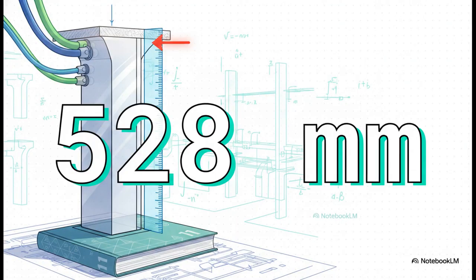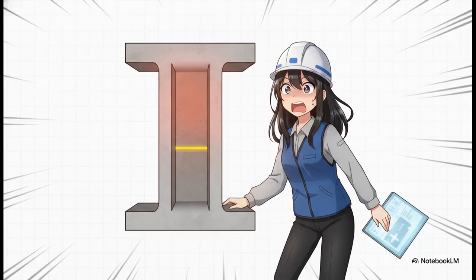So we plug that 600 millimeter width into our ratio formula. We take that ratio straight to Table 11 of the IS 1343 code for bonded tendons, and we calculate our neutral axis depth, XU. The math tells us XU is exactly 528 millimeters from the top. And here is our plot twist. Our calculated neutral axis depth is 528 millimeters.